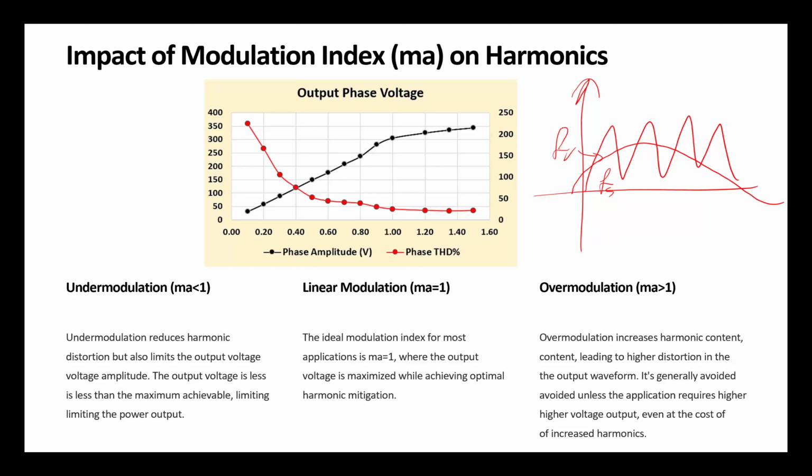Anyone has any idea? What is the significance of the reference frequency? What does it give us? What's the output? If I say the reference frequency would be 10 hertz, what would be the result of that at the output of our inverter? 10 hertz of frequency at our fundamental. The frequency of the reference signal is the frequency of our fundamental.